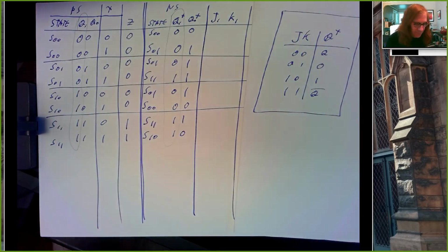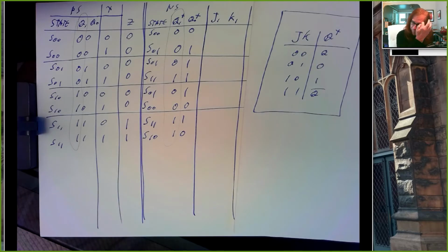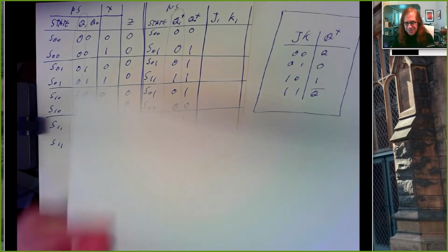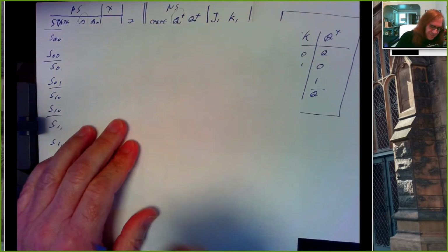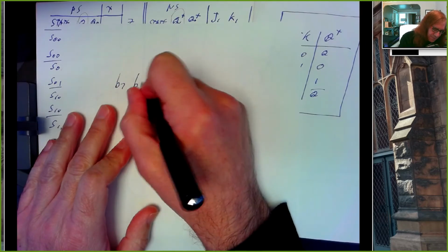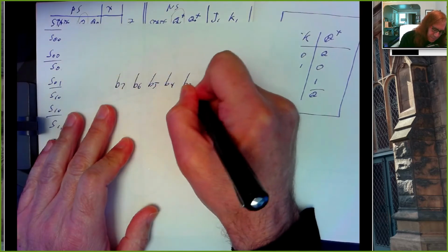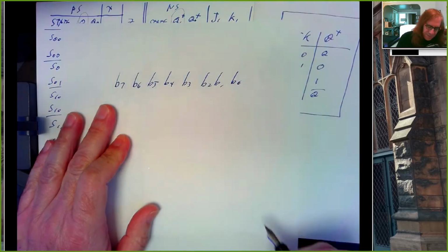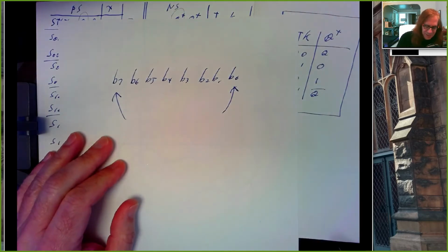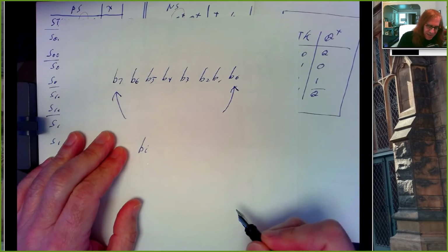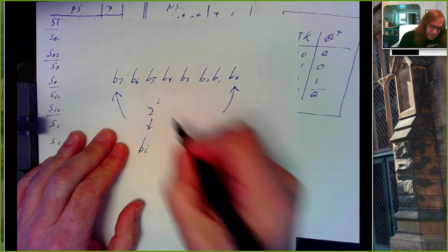Why do you do 1 before 0? I know in programming, everything normally starts at 0, and I don't really understand why starting at 1 and then doing 0 is done. It's fairly arbitrary, but when we do programming and you have an 8-bit number, we number them like this. This is considered bit 0, this is considered bit 7. And the reason is, if this is bit number i, its weight corresponds to 2 raised to the i.